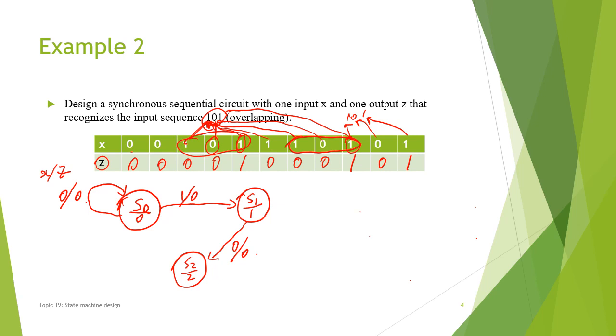But then let's go back to this state. What happens if we detect a 1? Like in this case, we first detect a 1 here, but then here we detect another 1. There will be no progress, no 1, 0, 1, right? But we can use this 1 as the first bit, so which means we still detect 1 bit of the data, so it will stay here.